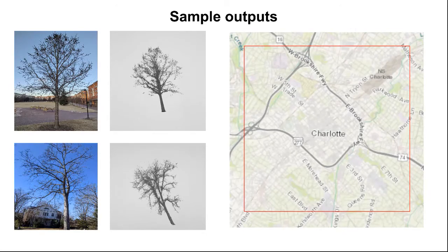And we are planning to use Charlotte as our study area because Charlotte has a higher resolution LiDAR data. It has QL1 data, which has at least 8 points per square meter, and Charlotte has even more points than that.